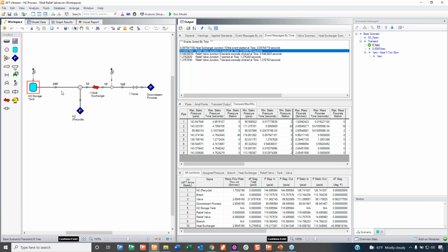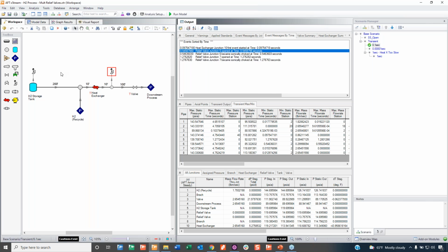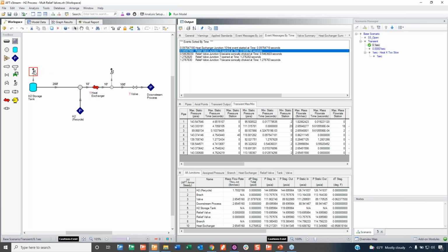And then to open. The relief valves are set at different set points, where this one's set to blow at 125 pounds. Yes, I'm using imperial units or US units, because that's where I am. Sometimes I'll switch around, but just bear with me if these aren't your normal units. And the other one is at 115. So this was 115, 125. There's a 10-pound difference. That's pretty significant. So I guess that kind of makes sense why this one would blow first.